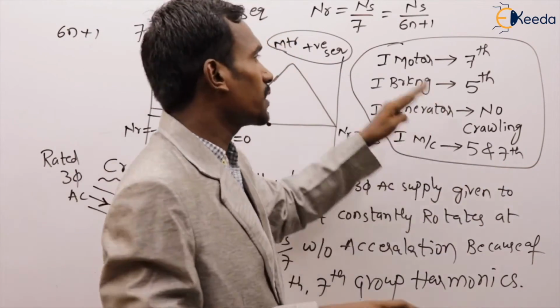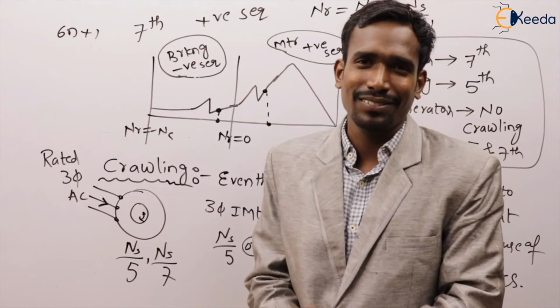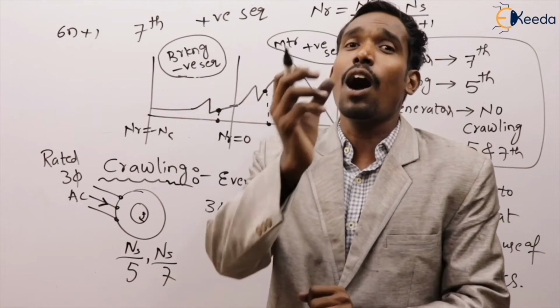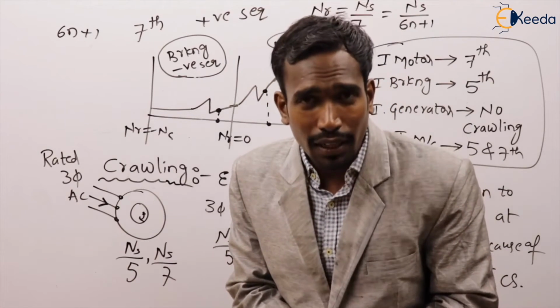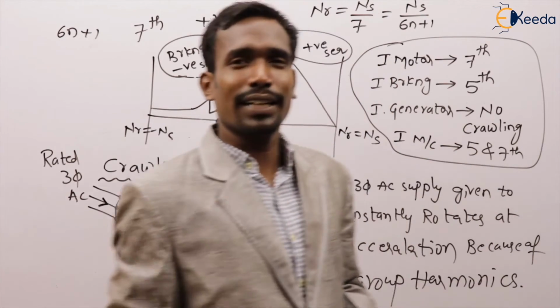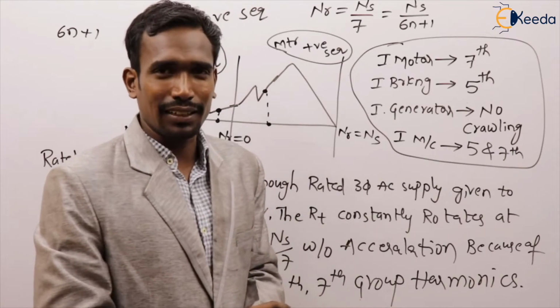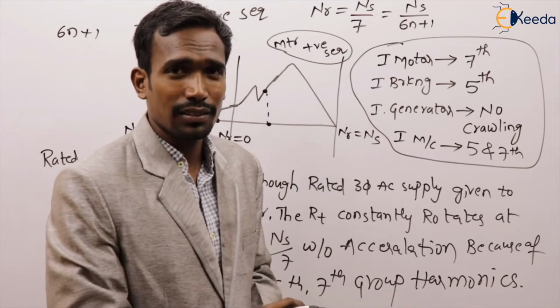Okay, so this is about crawling. I know crawling is there. How can we eliminate the crawling? Tell me. By using short pitch winding, we can eliminate the crawling.